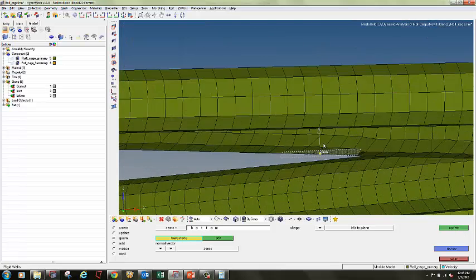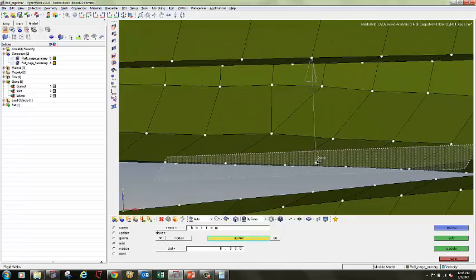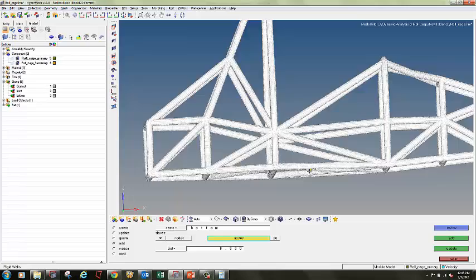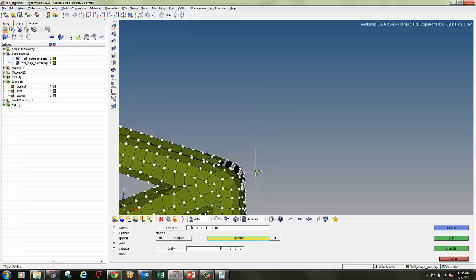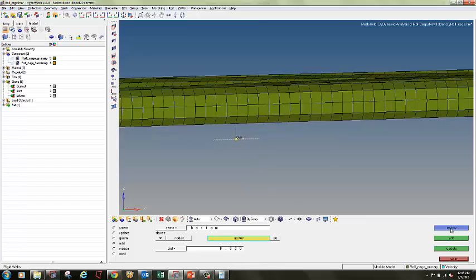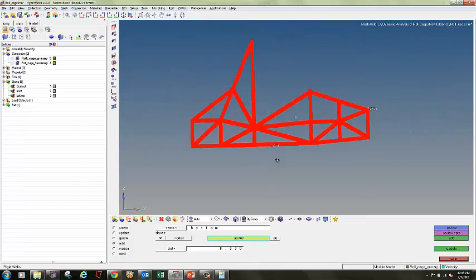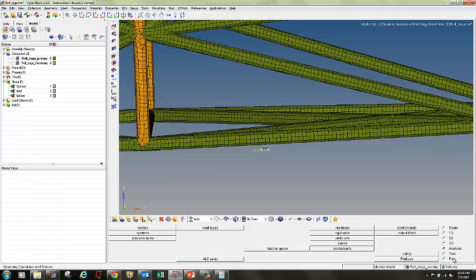So we can see the direction is set. If it's in negative direction, then only we have to pick N1, N2. If the direction is positive, I will pick directly the axis here. Now add nodes, all. We will deselect this one. Also we will deselect this one. So make sure to deselect the node of the wall and click on add and review. You can see all the nodes are in contact with this wall. Then I will click return. So my wall definition is done.